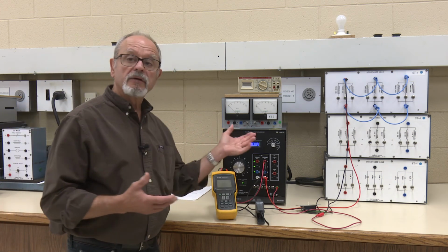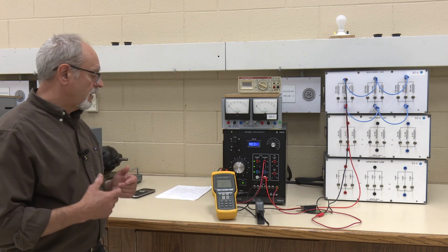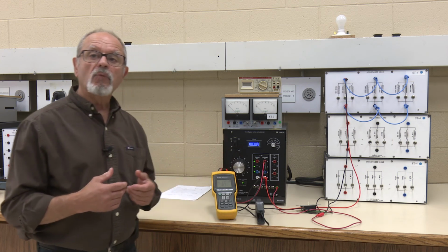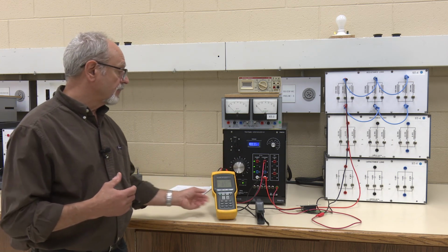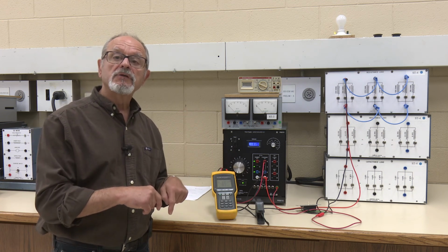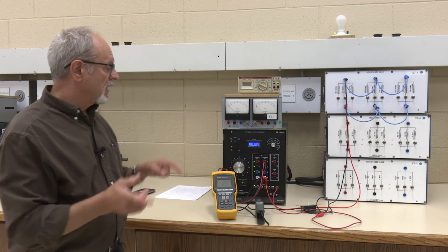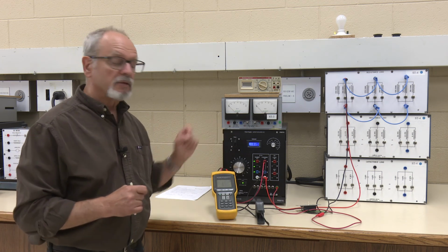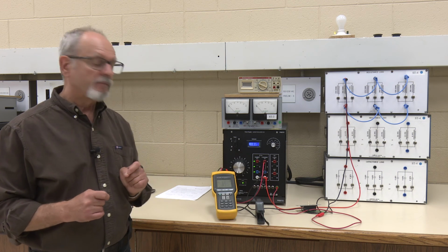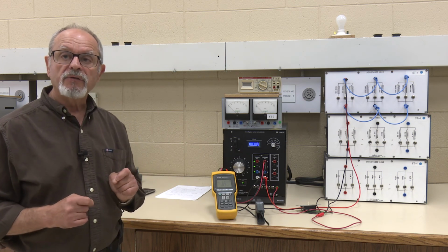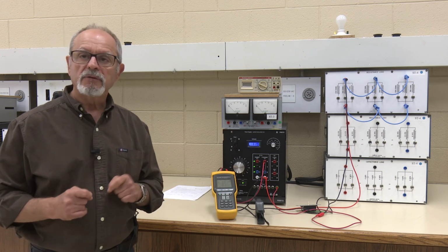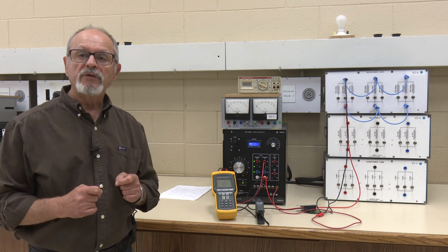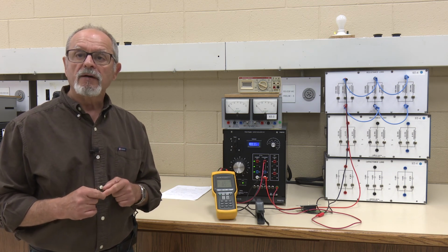So the lesson here is that with the switcher, as you start to reduce the load, you actually create more and more distortion to the current waveform. And if there are enough switchers in your plant, you could actually create a considerable amount of distortion back on the line side of the utility, which is not a good thing, because that's not being a good corporate citizen. You're going to affect all the other customers on that point of common connection at the substation.